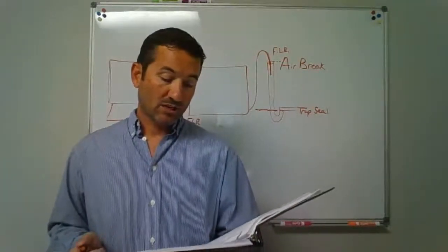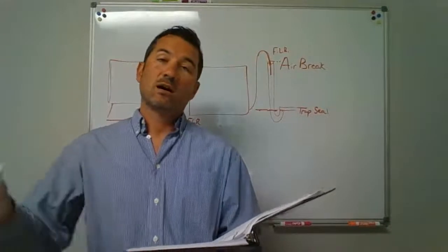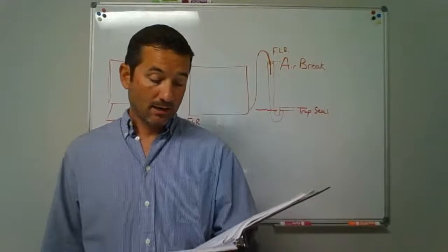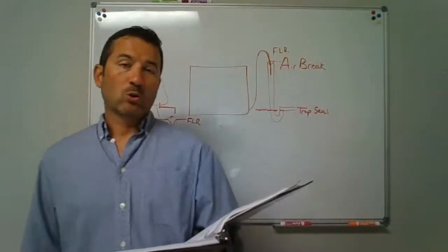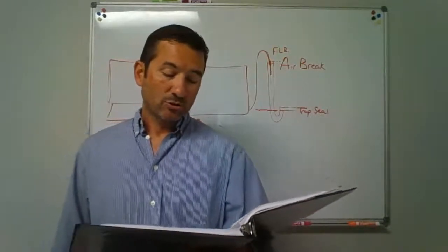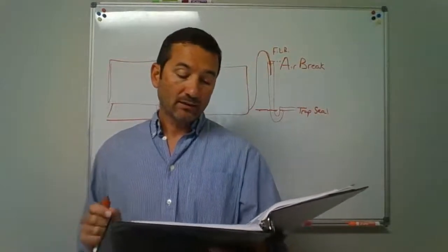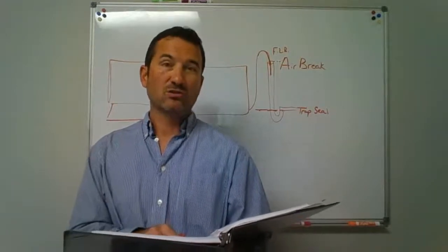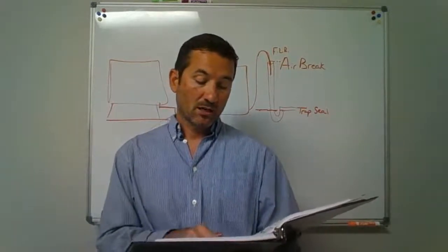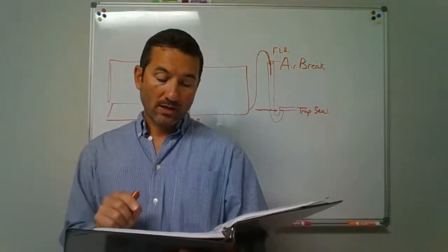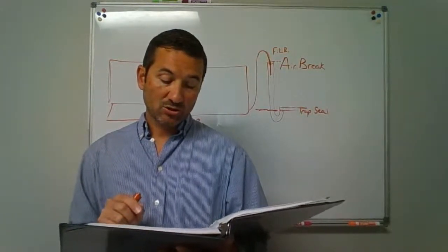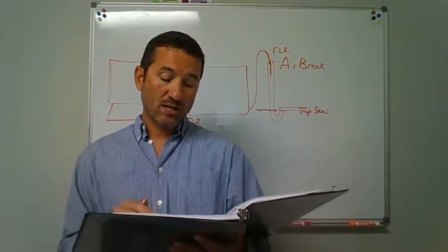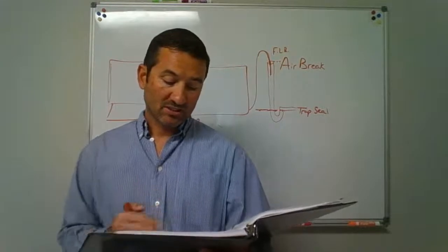You can read about the protection, the process as far as maybe for cooling purposes, as cooling air flowing through that air gap. But where is it required? What's going to require us to have to do this? 802.1. Food handling equipment in other than dwelling units. So other than residential. Okay. So you go to a commercial place where you've got food handling equipment, clear water waste, dishwashing machines and utensils, pots, pans, and dishwashing sinks shall discharge through an indirect waste pipe as defined by these next sections here. Okay.